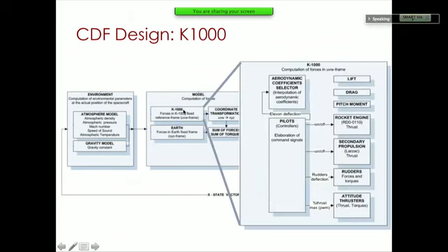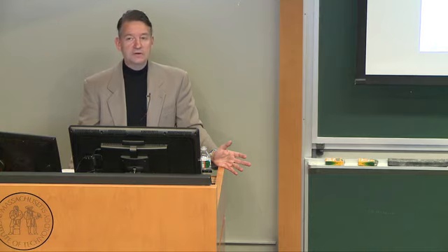So if you zoom in on one of these, for example this force model, the computation of the forces, there are two frames: the Earth reference frame, and the body-centric frame of the vehicle itself. In this case you have the aerodynamic coefficients. You have the forces: lift, drag, pitching moment, and then you have the actuation. This assumes the pilots are in control: the rocket engine itself, secondary propulsion, the rudders, and then attitude thrusters. You need those especially once you're out of the atmosphere.